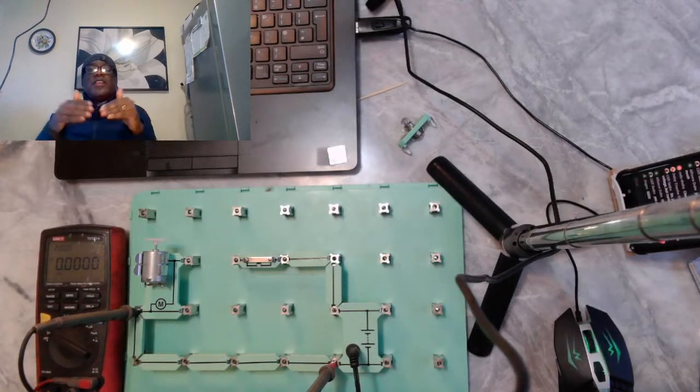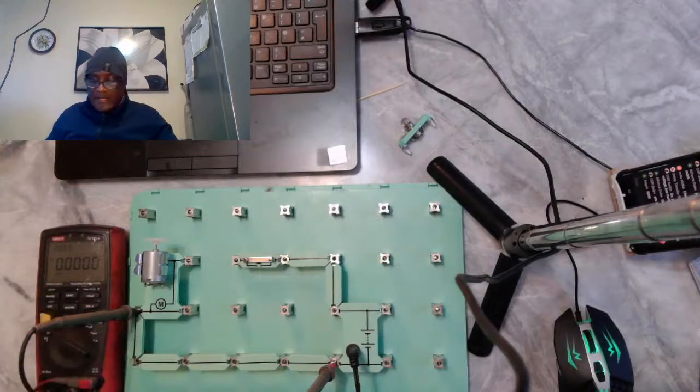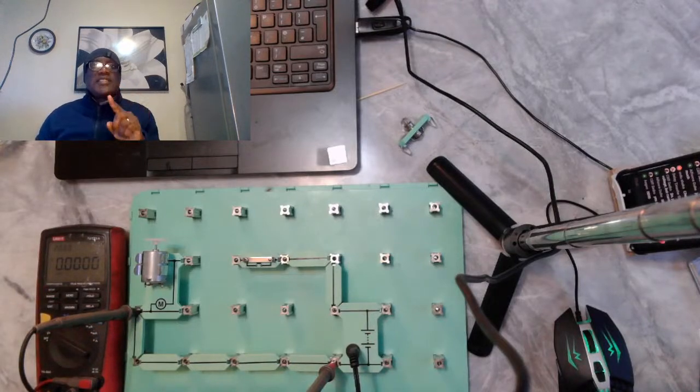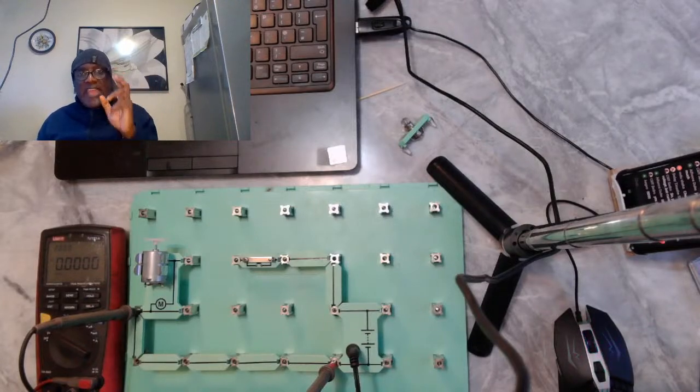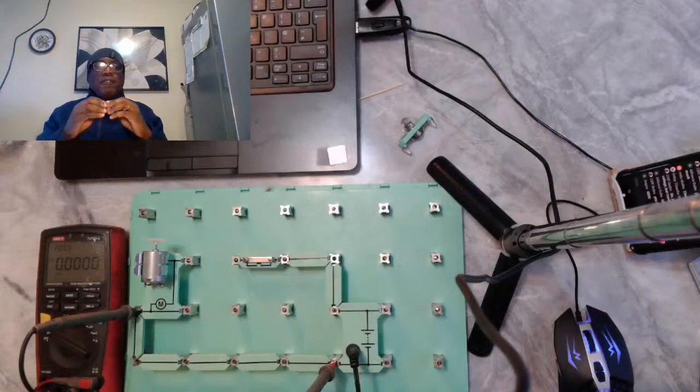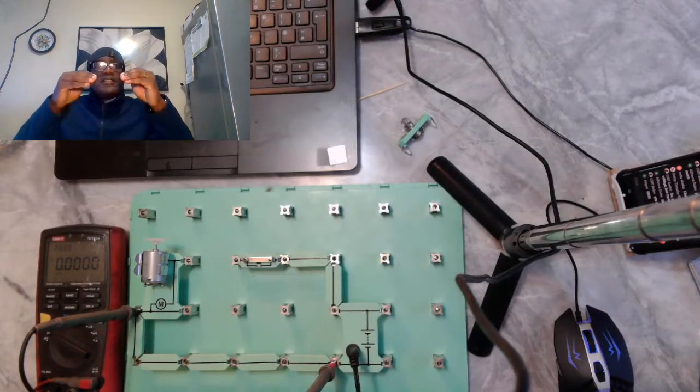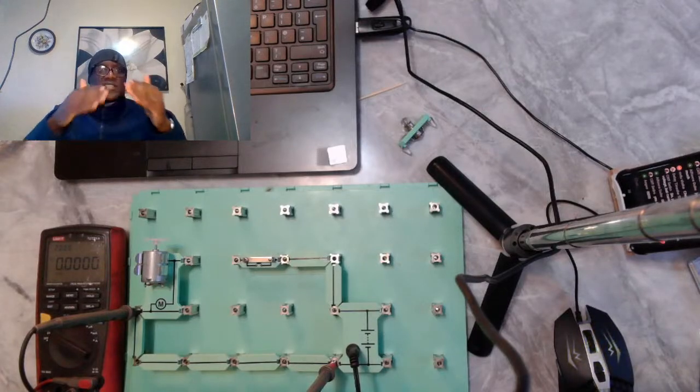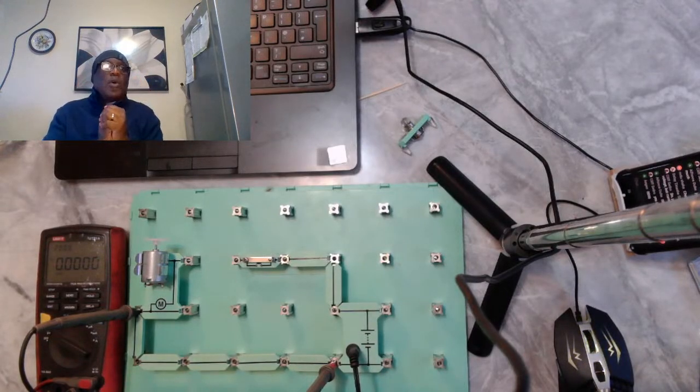So we are on the negative side. We came negative and we are negative. Remember what we said: whenever we have an open in a circuit, the voltage will be found on the side that has got that open.